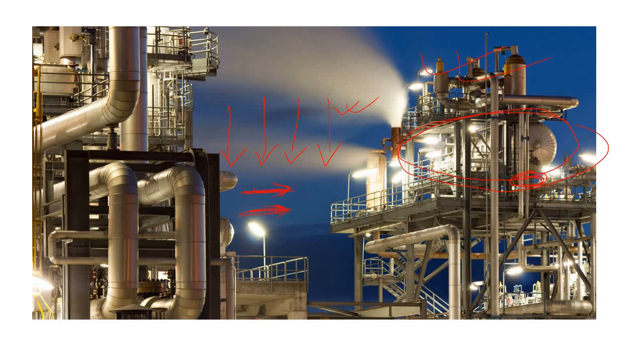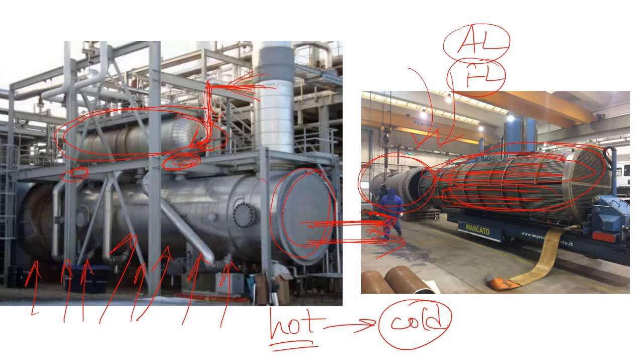So what is the actual magnitude of lateral load and why is it coming? This is coming because of the bundle pull extractor. What is that? Inside this exchanger there is a bundle of pipes, and after a certain time period you need to pull out all these pipes from the shell, clean them, and then reinsert them within the shell or exchanger.